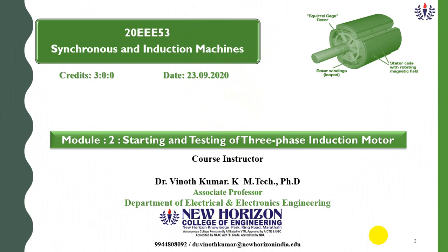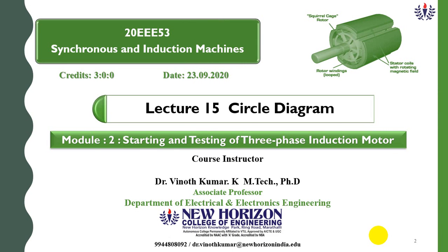Good afternoon to everyone. Today my topic is lecture number 15, circle diagram. Last class I explained the testing methods of the three-phase induction motor. There are two testing methods: one is the no load test, another is the blocked rotor test. Now, by using these two tests, we are going to construct the circle diagram of this three-phase induction motor. The purpose of this circle diagram is to predict the operating characteristics of the machine.